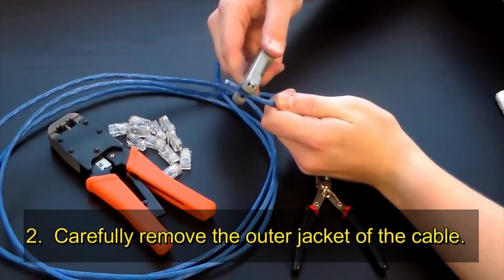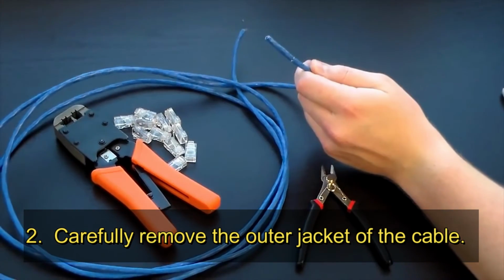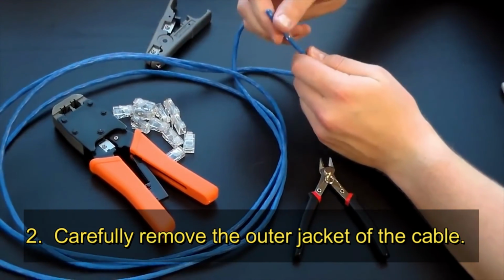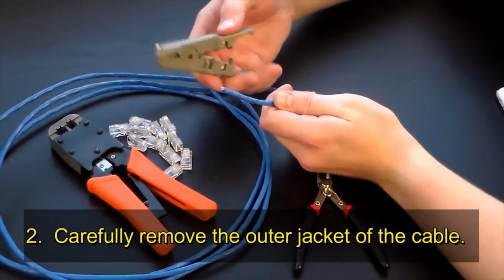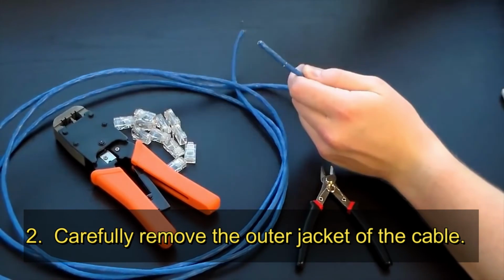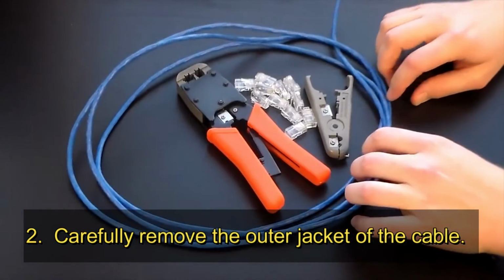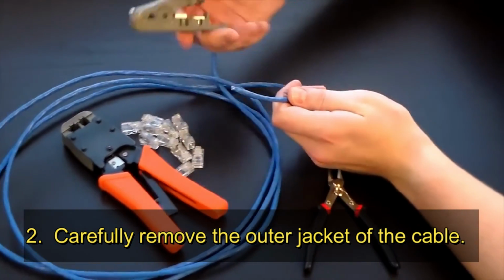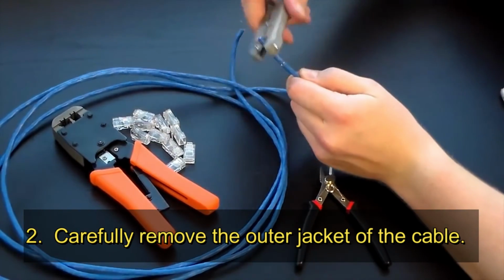Step number 2. Carefully remove the outer jacket of the cable. Be careful when stripping the jacket as to not nick or cut the internal wiring. One good way to do this is to cut lengthwise with snips or a knife alongside of the cable, away from yourself, about an inch toward the open end. This reduces the risk of nicking the wire's insulation.